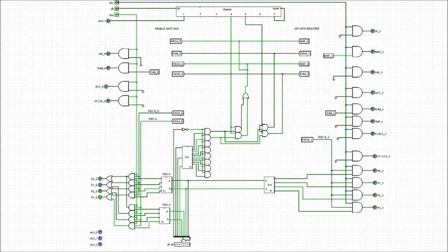and that's going to come from these 2 bits here, this bit and this bit, which is going to be a value of 1 and 1, which is going to choose this one here, which is going to choose register 3. So really what we're doing is we're taking the contents of register 3 and then we're going to be putting it into the memory address register whenever the clock comes along. So let's go up to the top level and we'll see that happen.